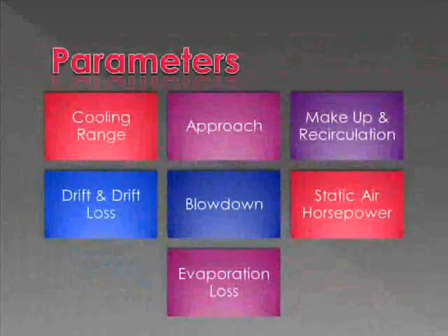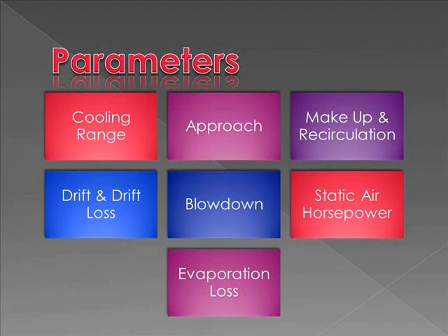Moving on, here are the different parameters that also need to be considered in cooling tower operations: the cooling range, approach, makeup and recirculation, drift and drift loss, blowdown, static air horsepower or SAHP, and evaporation loss.